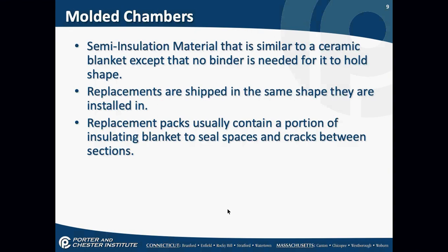Now, combustion chamber, again, your burner is pointed into the combustion chamber. The combustion chamber is usually a little bit larger than the burner opening. So to replace a combustion chamber, a lot of times it involves disassembling almost the entire furnace or boiler in the basement. So this is not an easy task. You want to avoid breaking the old combustion chamber whenever possible. They do wear down over time, but you don't want to be the cause of it.